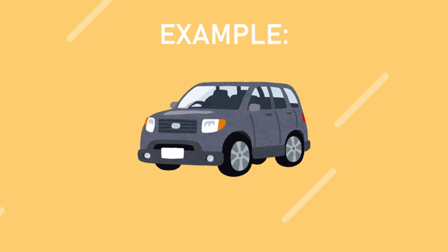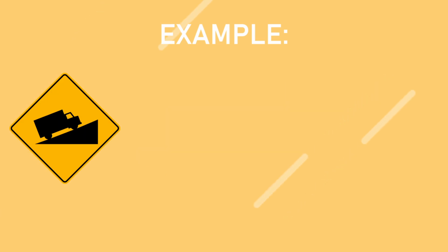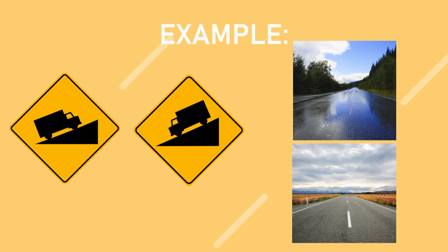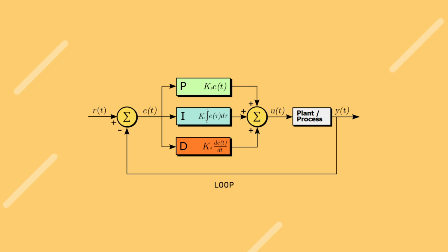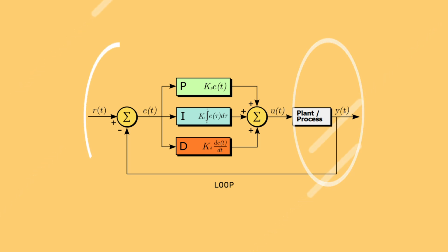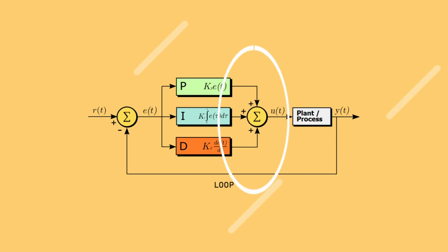One of the easy, well-known examples of PID control is the cruise control on the cars. Conditions like whether the car is driving on an uphill or a downhill, wet or dry road, the traction on the wheels can cause differences in speed. The PID algorithm fixes the measured or current speed to the desired speed with the least delay and overshooting by controlling the output of the engine.